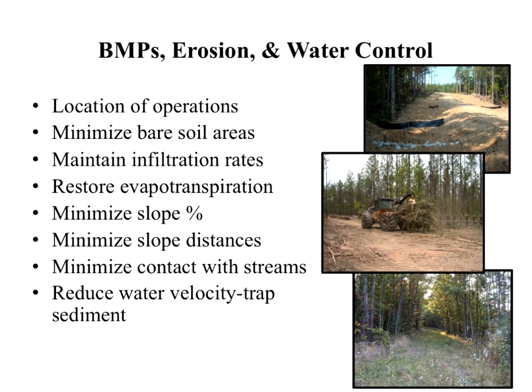For our roads, our skid trails, our stream crossings, we want to try to keep our slopes below 10% when we can. 10% is the point where sediment really starts to increase. We also want to minimize the distances on these slopes.